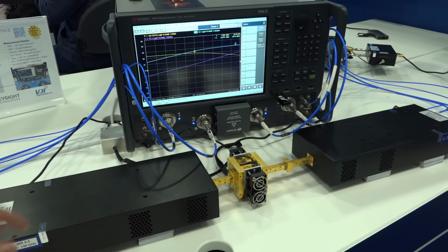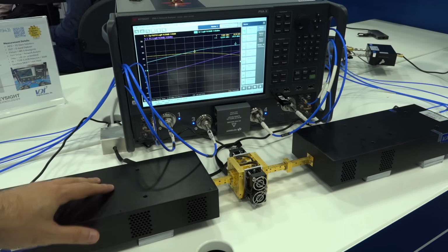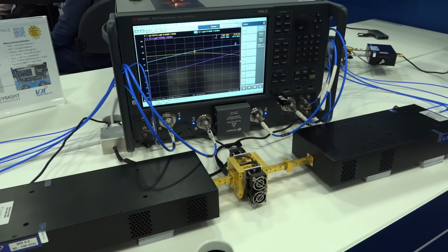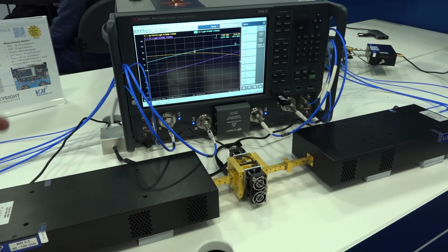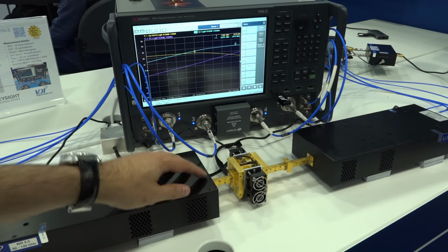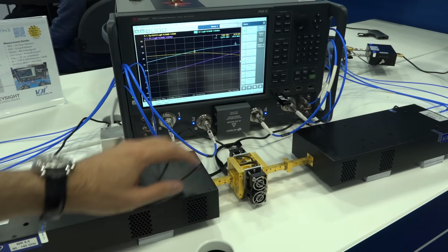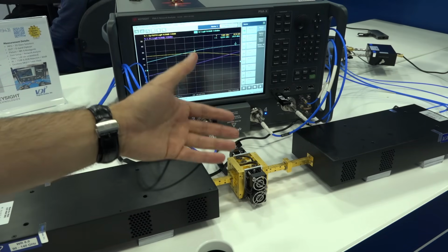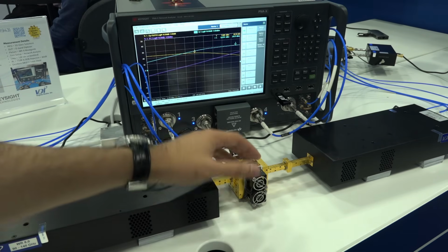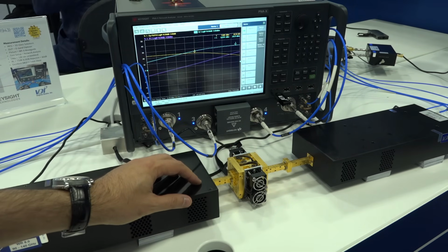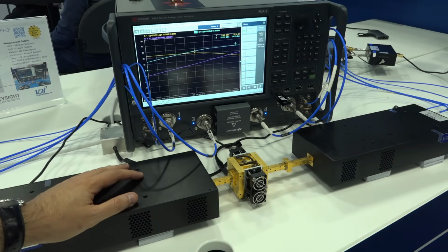So here at VDI, I also want to show you something interesting, which is their latest ultra-high power TR headsets for S-parameter measurement. This particular one is WR8, 90 to 140 gigahertz. So traditionally, network analyzer heads have always been limited in output power, particularly at these frequencies, especially if you cross 100 gigahertz. And the problem with that is, well, if you don't have a lot of output power, you cannot, for example, compress amplifiers that you connect to the DUT so easily. Or if you have losses in your system, then you're eating into your dynamic range. It will become very difficult to measure.